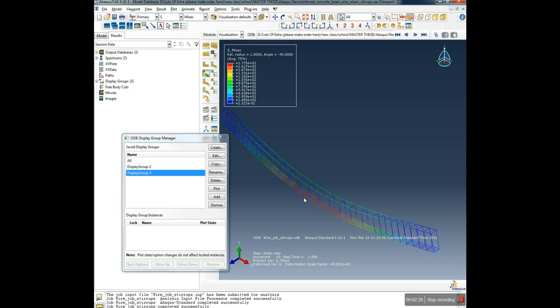And the stresses are much higher in the longitudinal rebars. So because this kind of reinforced concrete beam is subjected mainly to bending. If it was, instead of the beam subjected to uniform distributed load, if it was a column subjected to moving supports, or subjected to an earthquake, and check my video with the earthquake, just the link is in the description. If it was like that, then the shear would have a major influence. The shear forces would have a major influence on the response of the rebars by means of stresses.